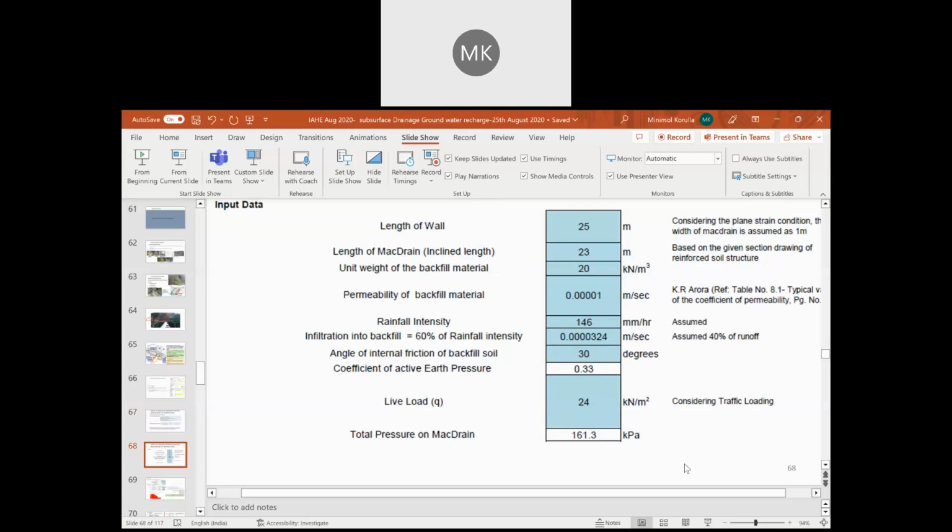Okay. So one needs to ask, when we are selecting a drainage composite, the most important parameters are permittivity and apparent opening size, CBR puncture strength, and maybe we can ask for the tensile strength also. And more importantly, with the pressure or force changes, whether any deformability is there and whether it will affect the permeability, that needs to be checked.